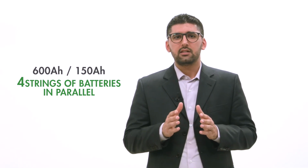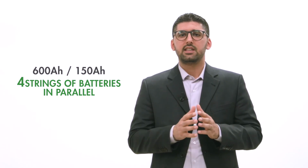In our case, we are going with a 12 volt 150 ampere hour battery. This means we need 600 ampere hour divided by 150 ampere hour, and that gives us 4 strings of batteries in parallel, producing a total of 600 ampere hour.